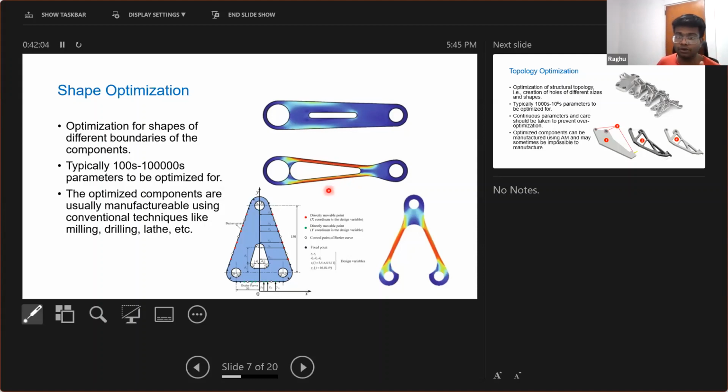However, here you should notice that you should choose something called design domains. So here you are choosing to optimize for this shape, this slot shape, and the outer cross-section shape. However, you are not optimizing for this shape or this shape. Why? Because this is where you are going to place the nut, right? You can't compromise on this circle ever, because you're going to place the nut there while wrenching. So this surface, this surface and this slot surface are called designable variables, designable surfaces, and the shape optimization algorithm would give you some optimized surfaces.